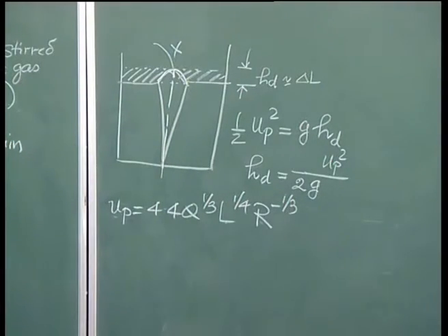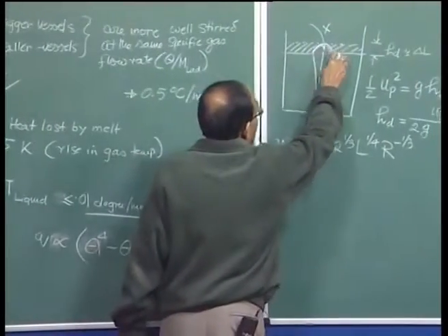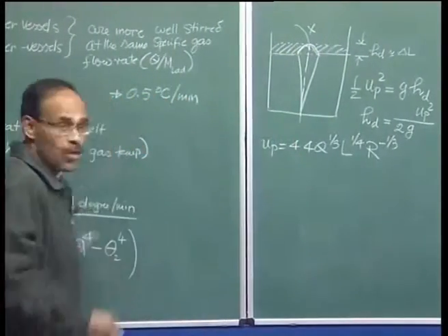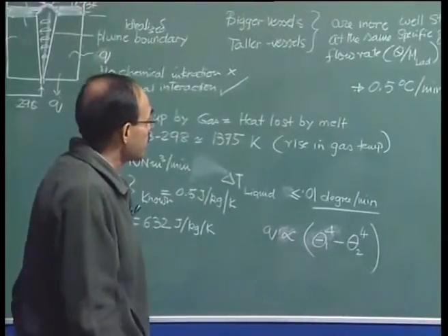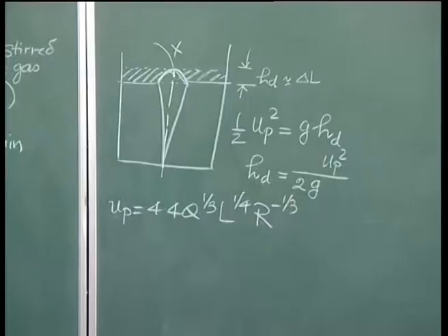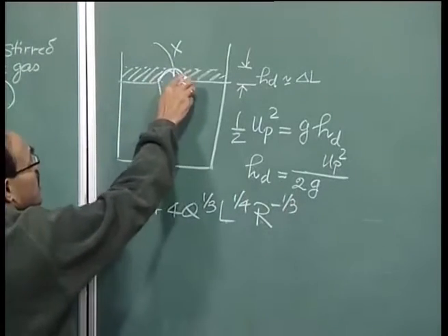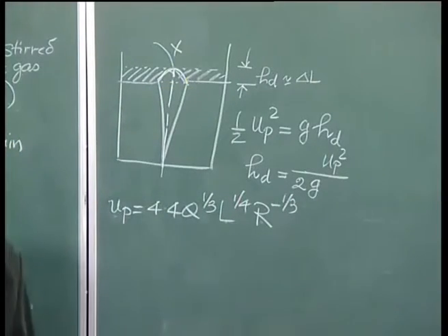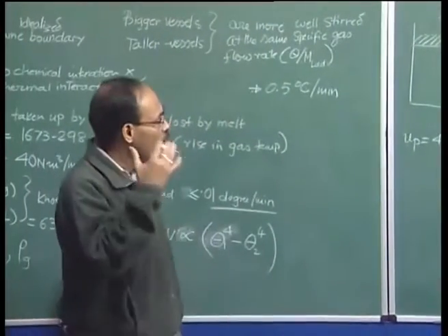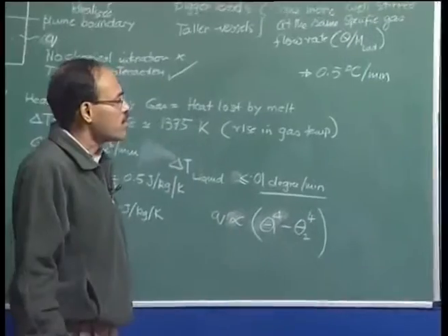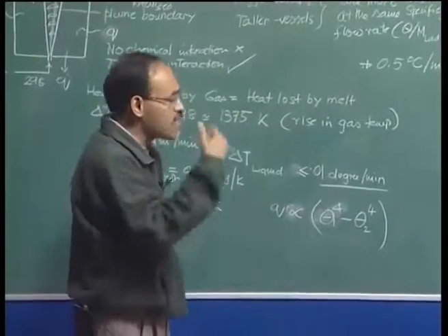Now, this slag eye is a very important aspect of secondary steel making operation. We are gradually closing down now on various aspects of inert gas injection. The slag eye area, for example, is a potential site of reoxidation, and particularly towards the final stages of rinsing operation or argon stirring operation, we want to homogenize the bath, mix the bath.